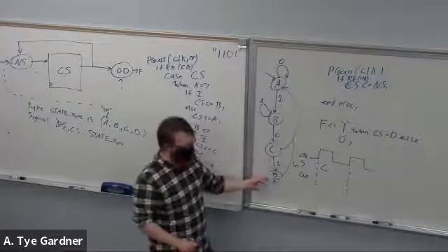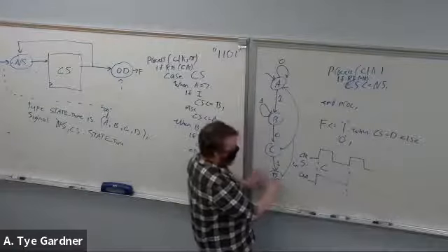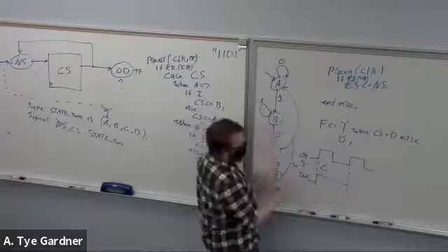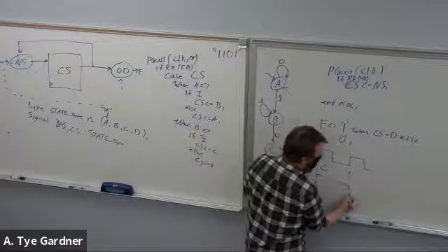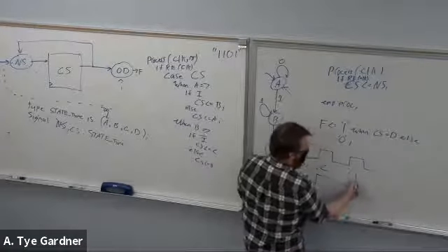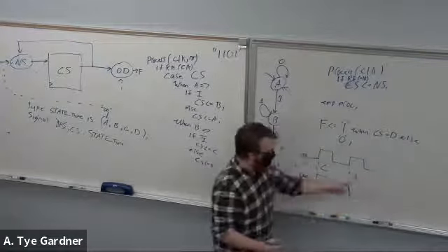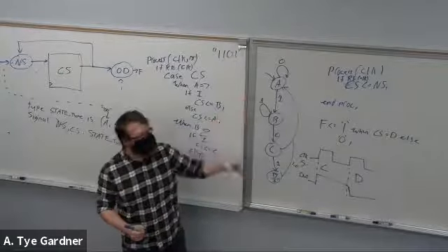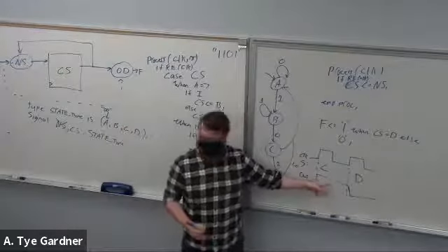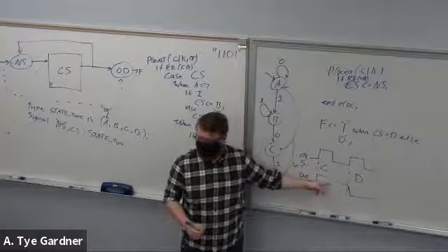And now I go into D, and D evaluates and goes, oh, well, my next state is A, so I'm dropping. So even though I'm in D, my current state, because of the if statement, is A, right? So this is actually off by a little bit as well. So be aware of that synchronization issue.